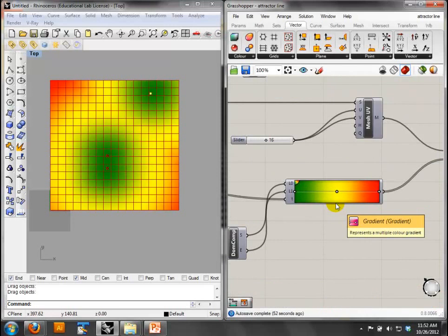So again, you can take any surface you want and turn it into a mesh, and you can apply color to it. And then you bake the color, and then you can render it. Lindsay? That was what I was saying. Yeah, the baking part actually needs a little component, which I'll put online tonight. You need a special component because in order to get the color to go to the right place, it makes a material for every single mesh and then figures out how to apply them for you. You can't just bake this; it'll just be gray. You've got to use the bake component that I give you.